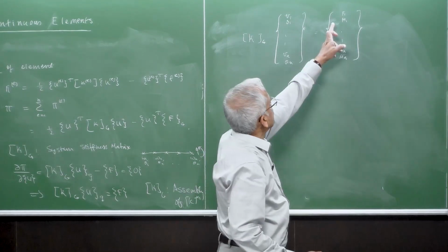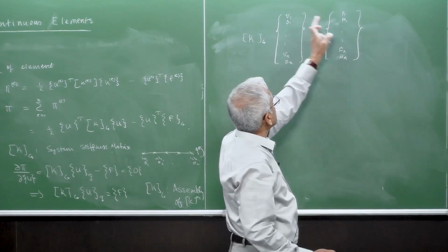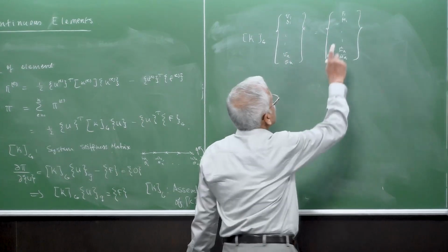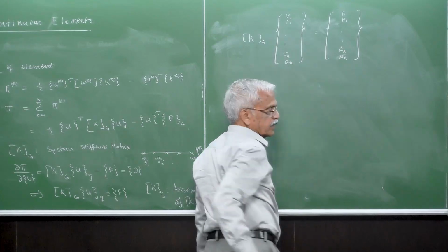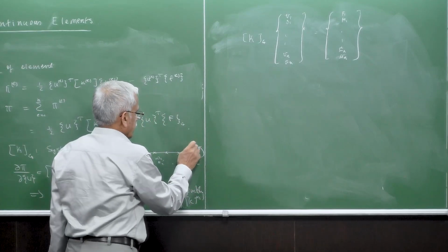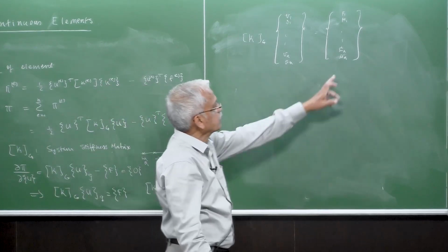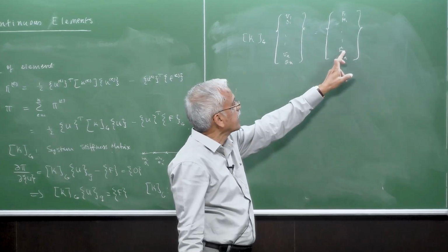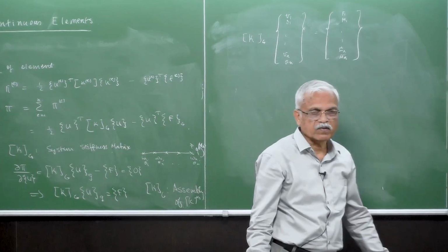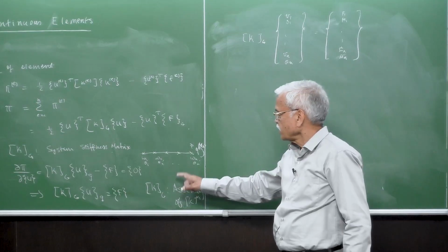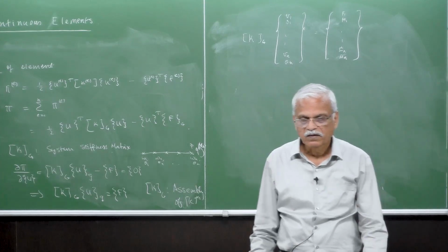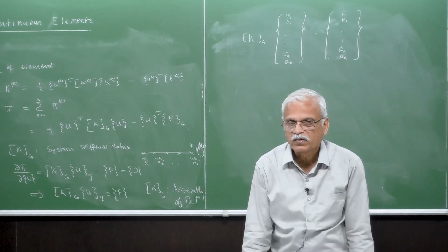So that is why you will find force when there is a deflection and the moment when there is a slope. Okay. So the moment is associated with the slope. So if you have at the node n a P and some moment, they should be added to this F, for P and M. So if you say M naught, it should be added here. And of course, this is in addition to whatever force vector you have there for the distributed force.